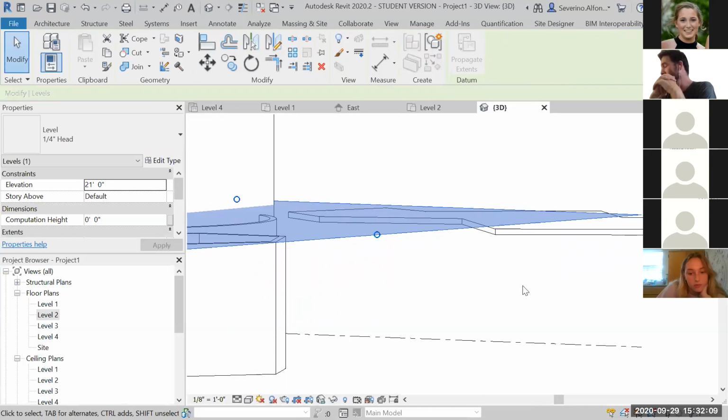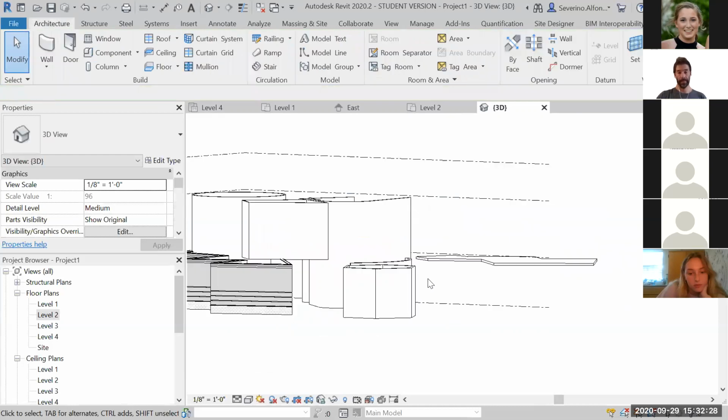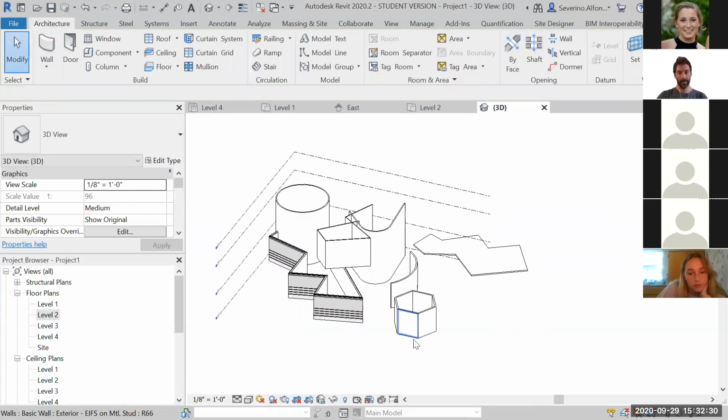Look at the floor where you are right now and where your feet are touching. That surface is actually where the invisible plane of the level is. It's not underneath the floor, it's not in the middle, it's exactly on the end of the finished material, let's call it. Any thoughts about that?